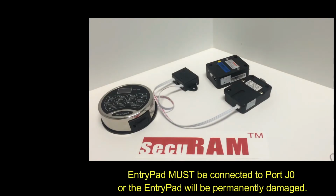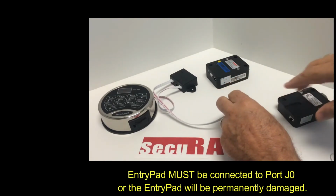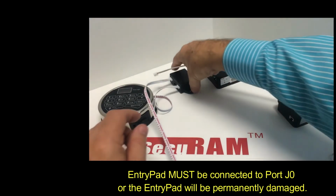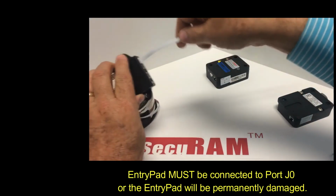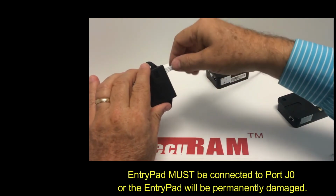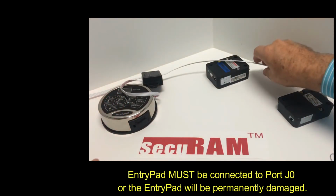So the first thing we want to do is disconnect lock number 1. This is done so that you don't confuse the system by looking at different things when we're naming it. So we've disconnected lock number 1, and now we're going to connect lock number 2. We do that by using another cable, plugging it into one of the other ports. I usually use the next port, so J2, 3, and 4, but it really doesn't matter. Once you've named it, it doesn't matter which port it's connected to.